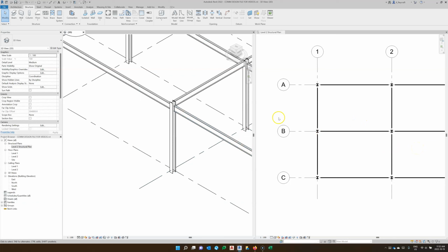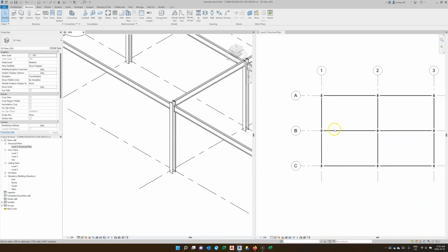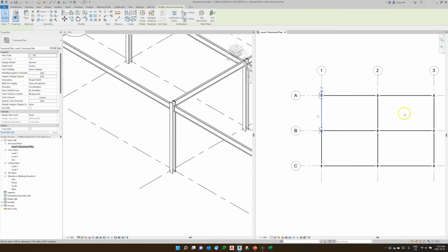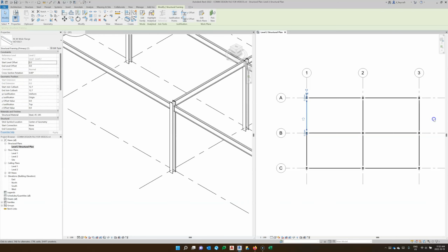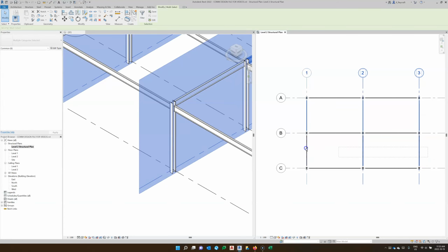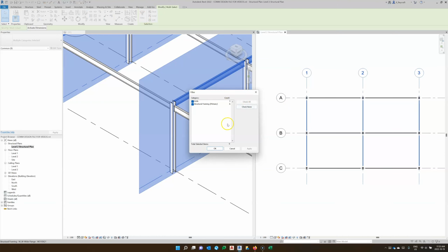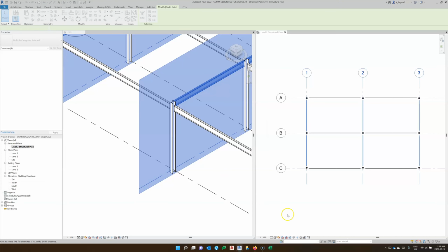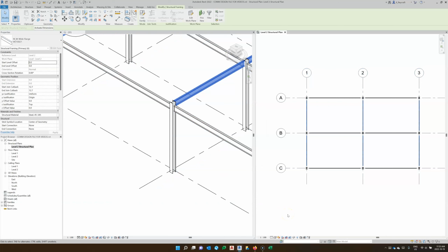So now what we'll need to do is take these beams. Actually, I'll just use the same method here. Crossing, hold down the control key, crossing, and I'm going to use filter to unselect the grids. Now these ones don't have to support the open web steel joist, so you don't have to compensate for that heel, which is 63.5.